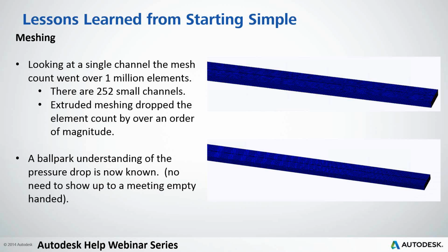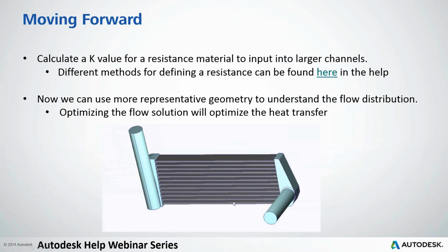So you have your triangle being extruded down the length, and it grows, so that down here my elements are much longer in the extruded direction, and we have them pretty tight in the beginning. I probably could have done some more tweaks, and I was playing with this before the webinar to see if I could get it a little bit further.